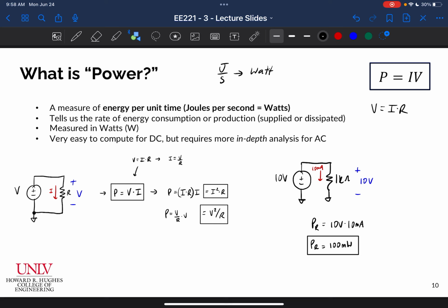This becomes really important in the lab specifically because resistors that you buy, like the type that I showed in module 5 of circuits 1, those resistors have a specific power rating. It depends on the resistor you buy, but if you buy those typical resistors that have the color bands on them, a lot of them are what's called a 1/4 watt or a 0.25 watt resistor. And so when you design circuits with these resistors, you need to keep this in mind, because if you design a circuit where this power dissipated by your resistor exceeds a 1/4 watt, then the resistor will start to melt.